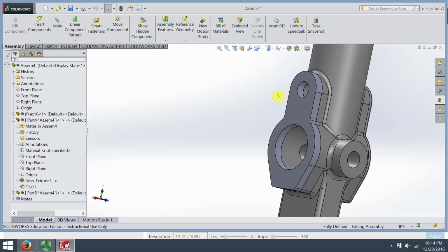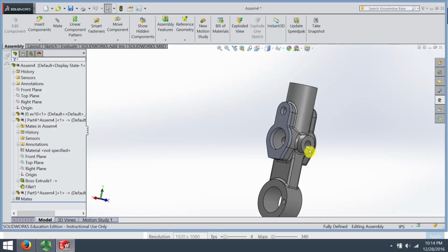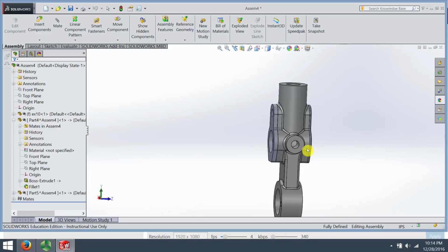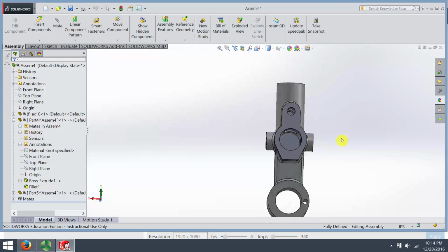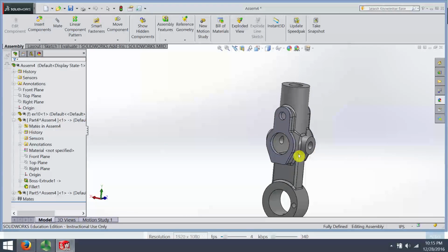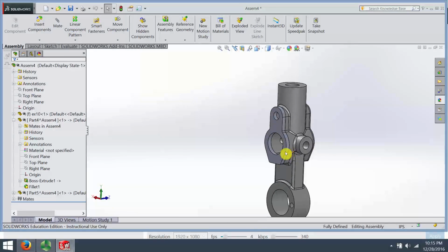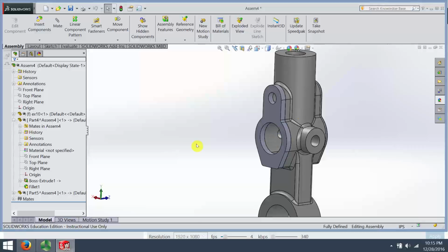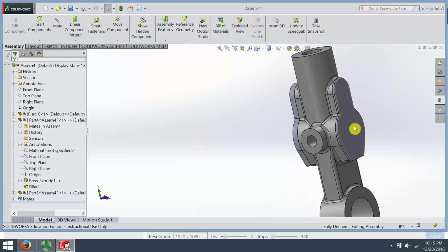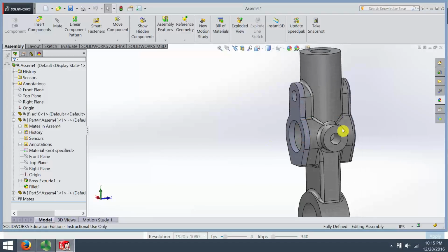So convert entities comes up a lot, because then we know that we've kind of traced that, and we get a relationship with the original geometry. Okay, so a couple of not so exciting parts, but you get the idea. Let's put in a shaft now. I'm going to have a large diameter shaft that goes in to here. I'm going to go ahead and leave this a closed plate so that it's not going to go all the way to the end of that, but then it'll stick out a little ways.